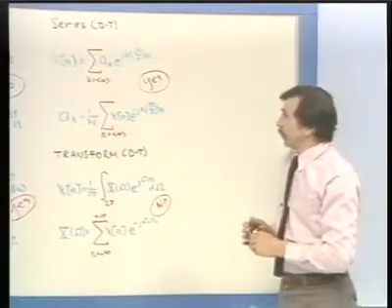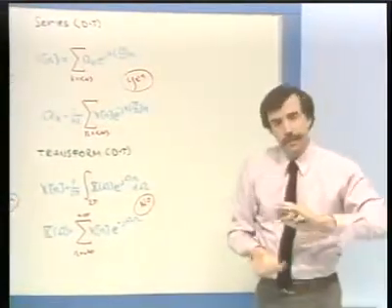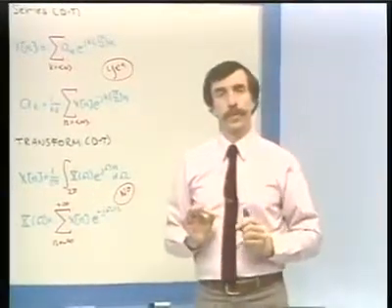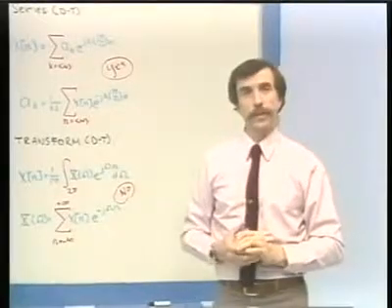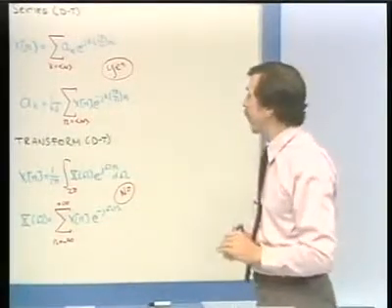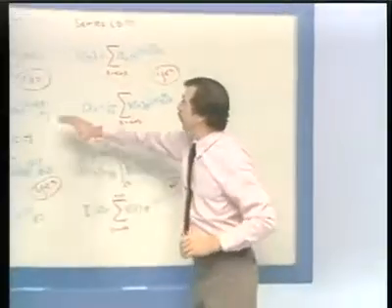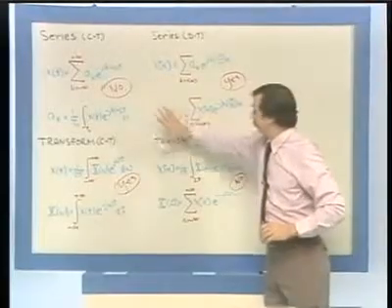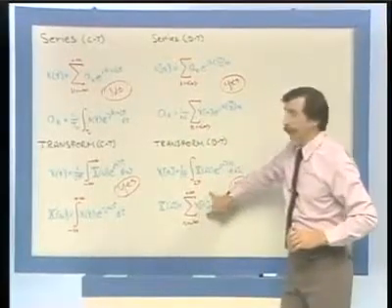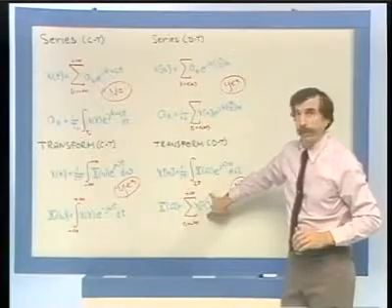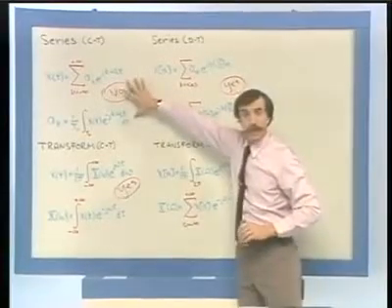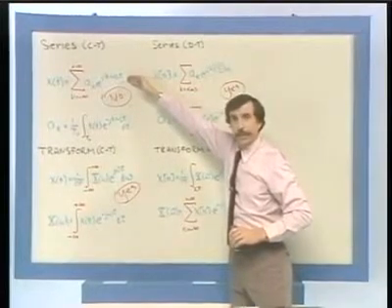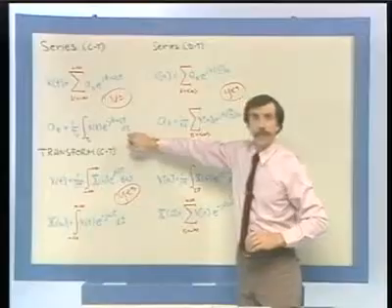OK, now, that says that there's a difference in the duality, continuous time and discrete time. And there's one more very important piece to the duality relationships. We can see that, first algebraically, by comparing the continuous time Fourier series and the discrete time Fourier transform. The continuous time Fourier series in the time domain is a periodic continuous function. In the frequency domain it is an aperiodic sequence.